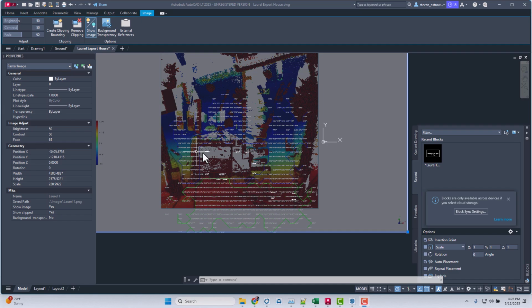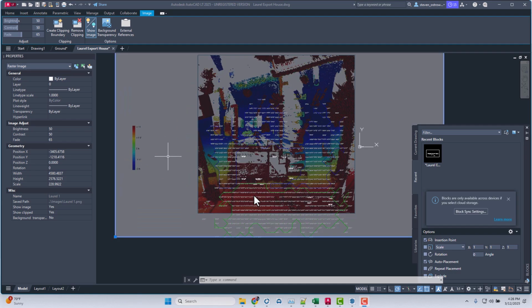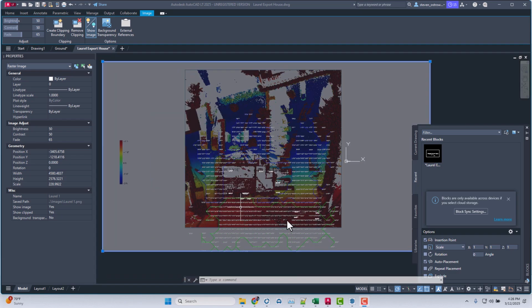We're going to show you how to do some spot elevations to bring into AutoCAD LT. Obviously, with LT, you can't bring in scan data, but you can convert that scan data on the tablet in the field to points that you can bring in. You can even bring in an elevation image, like you see here, showing a top-down view of a house. I have some contour points already in here, but everything's sloping away. So what we can do here.